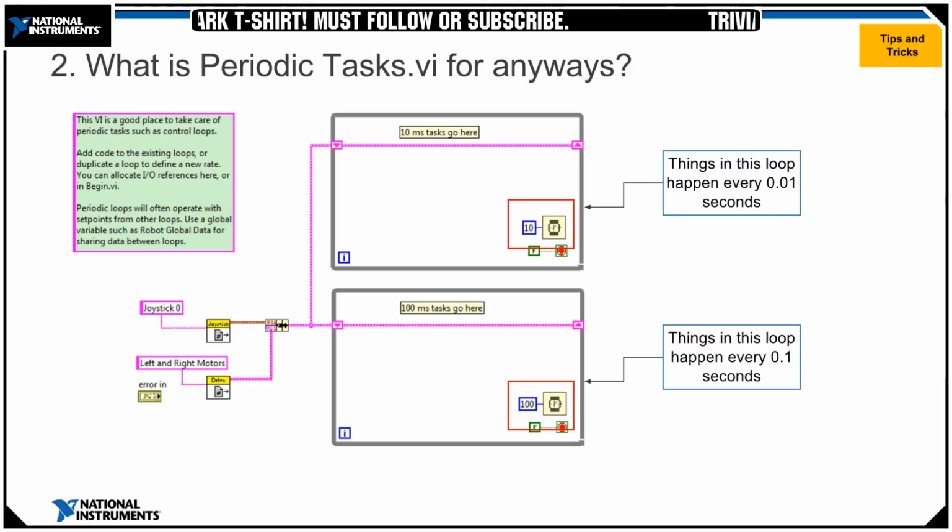If I wanted to add my own whatever to periodic tasks, in this case I've added a gyro sensor. You can see I've made a new loop because I decided I wanted my gyro sensor to update every 20 milliseconds. So I made a new loop for my 20 millisecond tasks. I set my get reference for my gyro. I called it gyro, I'm very original. And then I'm just getting the angle and printing it out to a global variable.